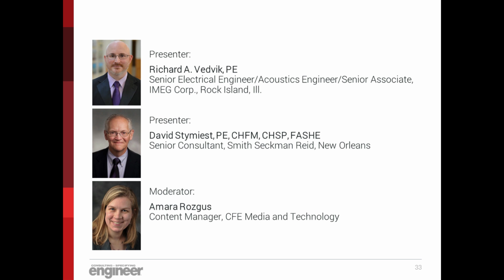Well, remember that we're still looking at resiliency. If you're going to have just 1 or 2 or single pathways, you're going to do that common mode failure analysis and what things can fail. The one thing I have experienced is that it does ease the conversation sometimes on, does it have to be on all emergency, or can we actually put some more of the stuff back on normal? So sometimes there's actually a cost savings that can happen when you're doing the 15 kV utility backup, because you feel like your normal is now more resilient than it would be otherwise. And you can go to maybe a more code minimum approach for normal and critical instead of critical 1, critical 2. But it depends, because you're going to have to perform the risk analysis defined within NFPA 99. Aha, it depends. Thank you.